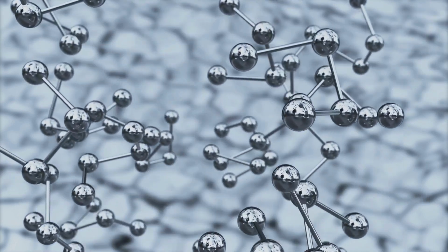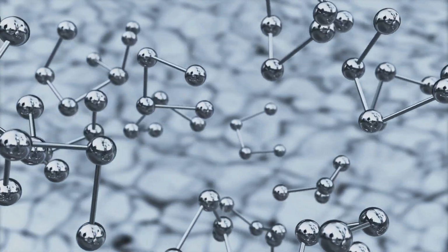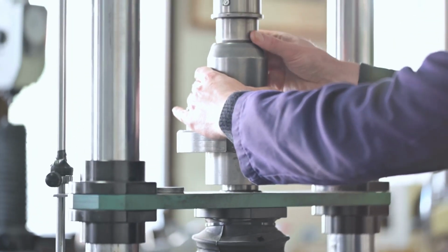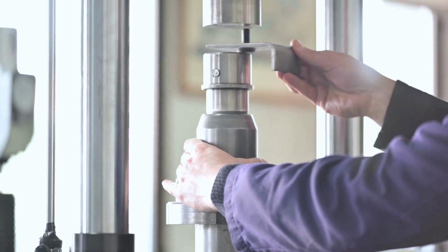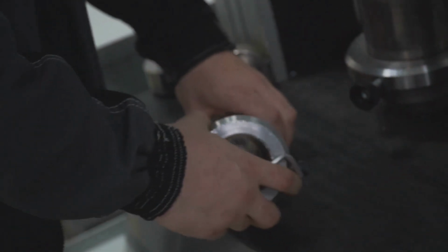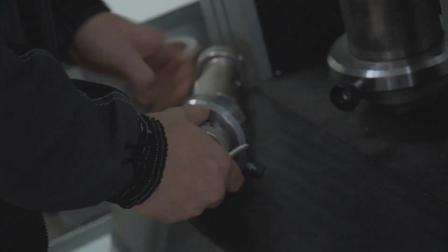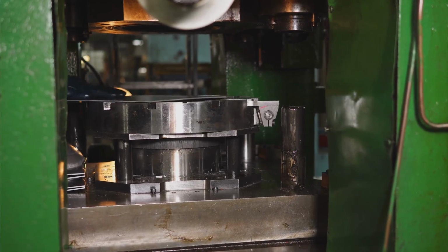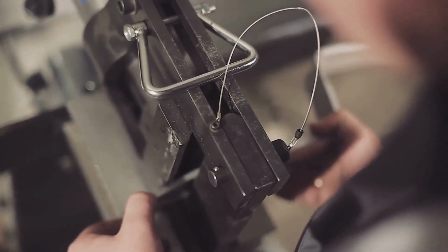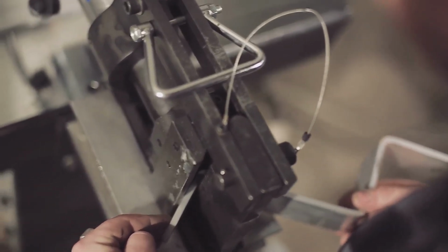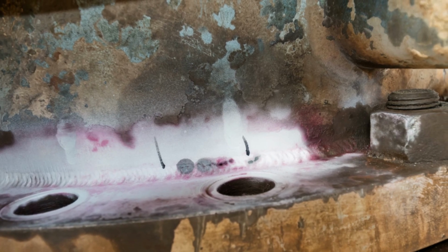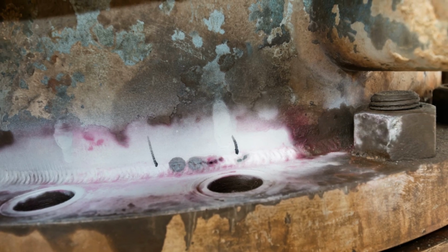Materials at an atomic level are a vibrant dance of atoms held together by electromagnetic forces. When we apply a load, we're essentially stretching or compressing these bonds. If the load is small, the atoms return to their original positions once it's removed. This is elastic deformation, but apply a larger load or apply smaller loads repeatedly and things can change. The atoms can be permanently displaced. This is plastic deformation. Fatigue failure is a consequence of this repeated microscopic dance, where cyclic loading causes irreversible damage.